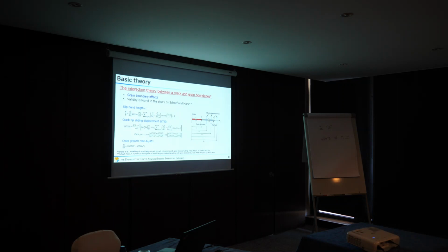I think you have a question. Yes, so of course one of the key inputs is the distance between the grain boundaries. You showed that you just used the intersect method in the horizontal and vertical direction, right? And in this particular example you showed, this grain is at 45 degrees. So why don't you use the actual distance between the two boundaries? Just for that particular case, the distance between the grain boundaries at 45 degrees would be significantly lower, right? The square root of 2. I would guess that's quite a big impact.